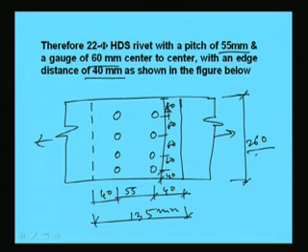So, as I was telling in last slides, the lap length should be as less as possible to save the material. So, here we see that lap length should be at least 135 mm. Now, we will see some other example.